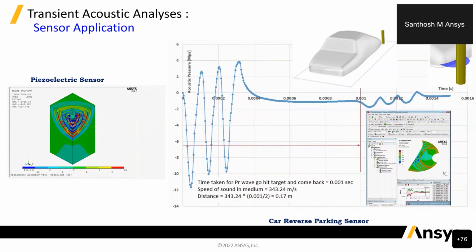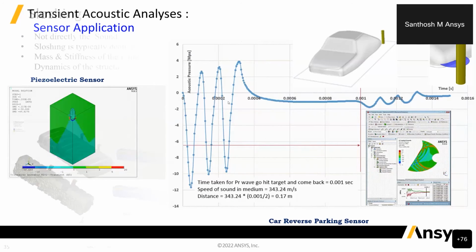When it hits any obstacle, the wave gets reflected, and the reflected wave is received back at the sensor. Depending on the time taken for the sound wave to travel, hit the obstacle and come back, it is possible to calculate the distance between the rear of the car and the obstacle. Those kinds of applications can be studied.